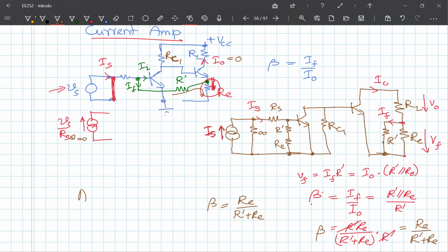in this case, A is equal to I out over IS. So this is without feedback. So once you have both these values, this is the one that we already have access to for this circuit. This is the current gain of this circuit. And if you have these two quantities, you can obtain the current gain with feedback, the input impedance with feedback, and output impedance with feedback. All these things we can find. Okay? So this is the current shunt feedback mechanism.